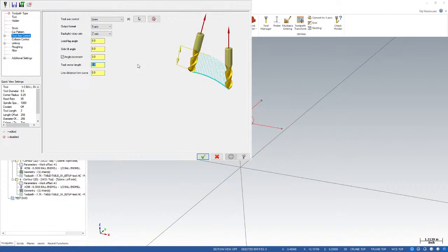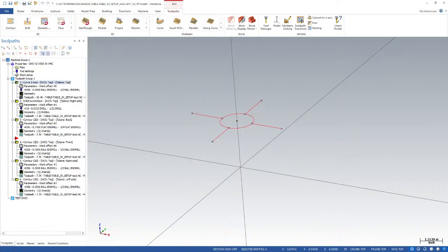But we can actually end up with a way to control feed rates, because there's also some logic that looks at the flute length, min-max on flute length, or min-max to pivot distance on a 5-axis machine in order to do some of this vector resolving. Plus, if you are machining a giant workpiece, sometimes it's just really hard to see a little small 1 millimeter or 1 inch vector. And you'll notice that the default in metric is actually 25 millimeters, I believe. So we can change this 3D vector length if we need to.